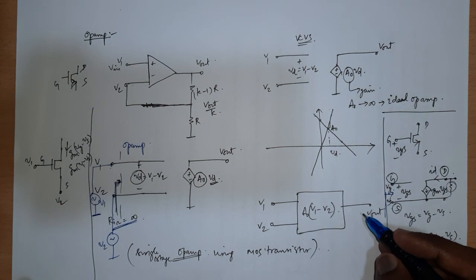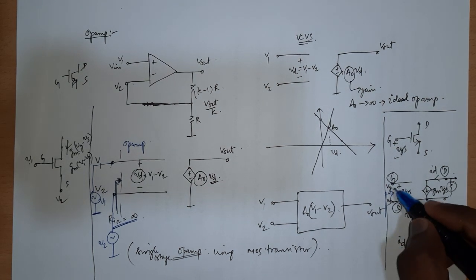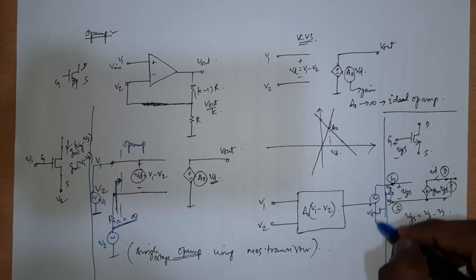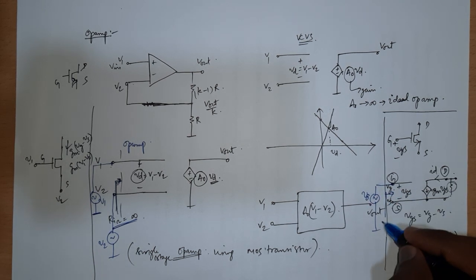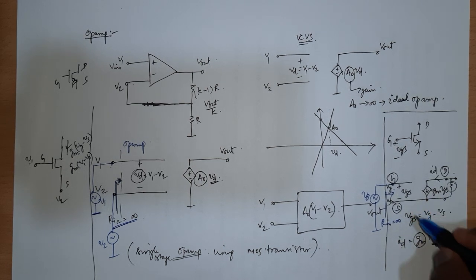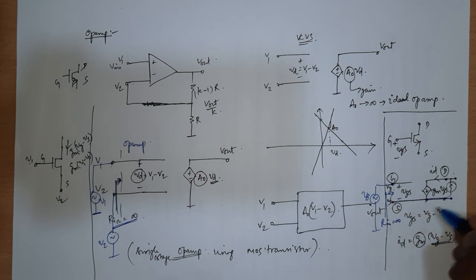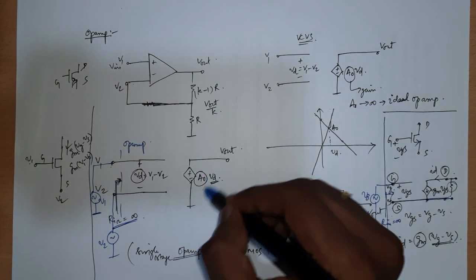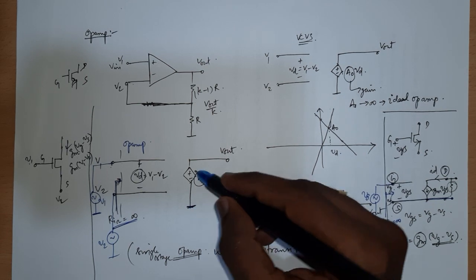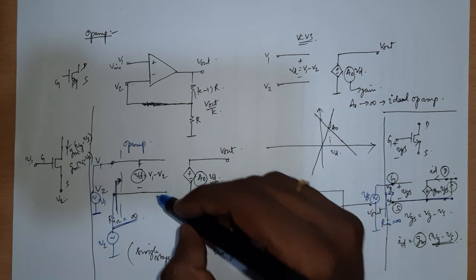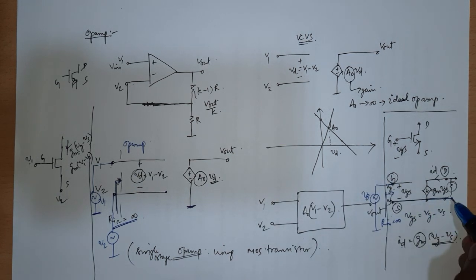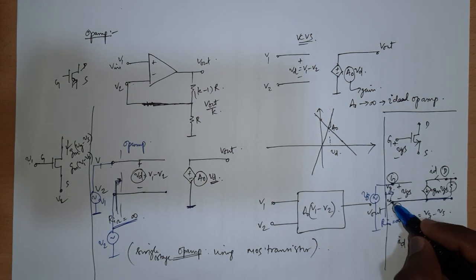Input impedance. Now you take a MOS transistor and connect an input, VG, between this point and ground. You look in this side, the input impedance is infinity. Good. But then you connect VS on the source side. The problem here is that this VS is essentially shorted all throughout. In an op-amp, one terminal of the voltage source is always grounded, so it is left open this side, but here it is completely shorted. So the source is common between input and output.